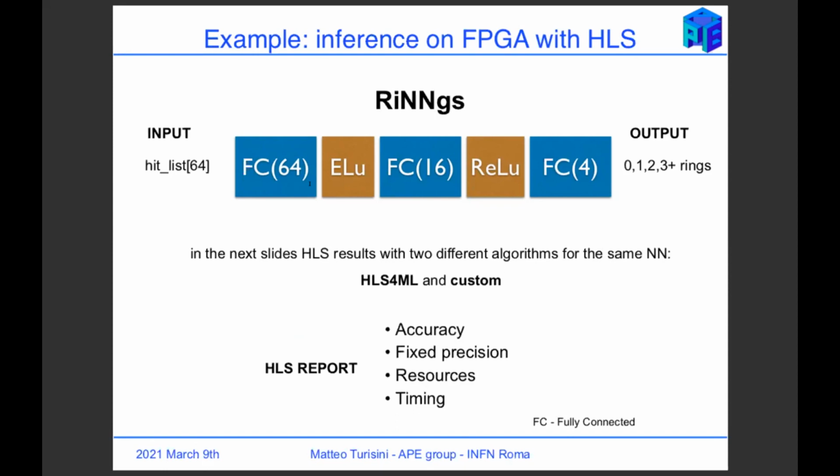This corresponds to checking the functionality of the algorithm like you do in every C code, and then moving on to something specific to FPGA. I will show you how the algorithm behaves if you vary the fixed point precision, and which kind of resources are needed for the computation, and of course check also the timing properties of the generated circuit.